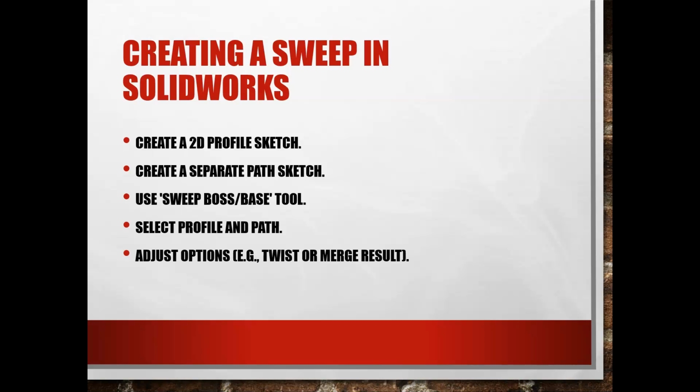That's if we're creating a piece, but if we're subtracting, remember we have to use the sweep, or in this case, I think it's called swept cut. All right, so you're going to have to do that one and that one.